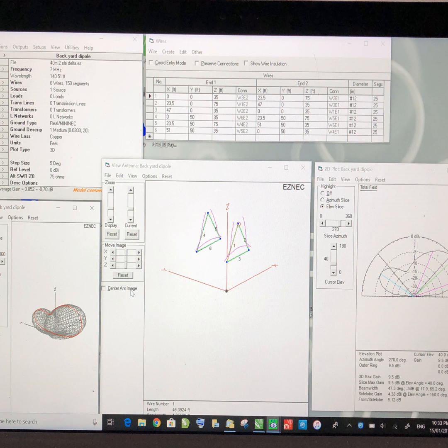So then sometimes you're looking more at a vertically polarized antenna, such as a vertical or a vertically polarized loop, and these can be really useful antennas. It just depends on what you're trying to do with the antenna. If you only want to make local contacts, a high angle radiator is absolutely fine. That's exactly what you need. If you want to work DX, you do need to try and concentrate on a design which will give you that low angle of radiation in the desired direction.